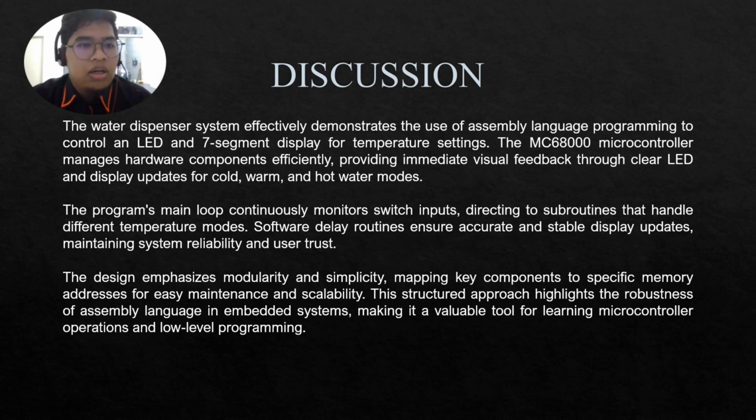For discussion, the water dispenser system effectively demonstrates the use of assembly language programming to control an LED and seven-segment display for temperature settings. The MC68K microcontroller manages hardware components efficiently, providing immediate visual feedback through clear LED and display updates for cold, warm, and hot water modes. The program's main loop continuously monitors switch input, directing to subroutines to handle different temperature modes. Software delay routines ensure accurate and stable display updates, maintaining system reliability and user trust.